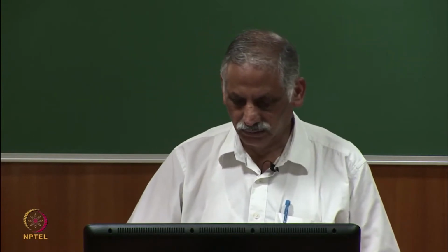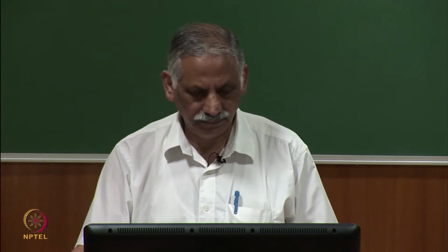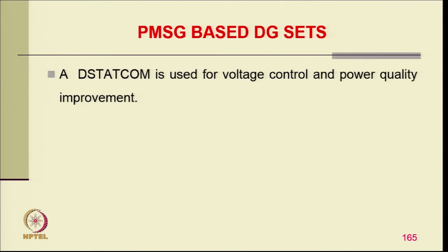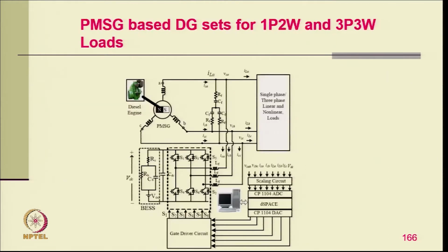So, we are discussing power quality improvement in permanent magnet synchronous generator based diesel generator sets. In the PM diesel based set, we use the distribution static compensator for voltage control and power quality improvement. A diesel engine runs at constant speed and is used as a prime mover.